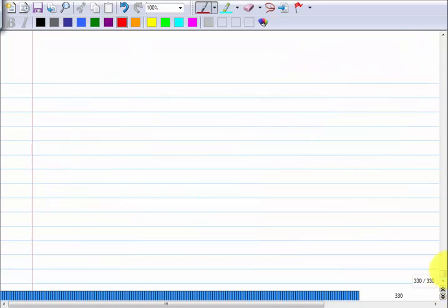So, now I won't show every possible circuit with the PNP. Just like you can convert every NMOS circuit to PMOS. How do you convert NMOS circuits to PMOS? Reverse. You first substitute all NMOS with PMOS and PMOS with NMOS. That will reverse the polarities of all transistors, and you have to reverse the polarities of all independent sources that set the bias. They could be current sources, they could be voltage sources. And then by convention, you draw the circuit upside down. That's all. So, I won't show this for every circuit, but I will show one circuit that we have made.